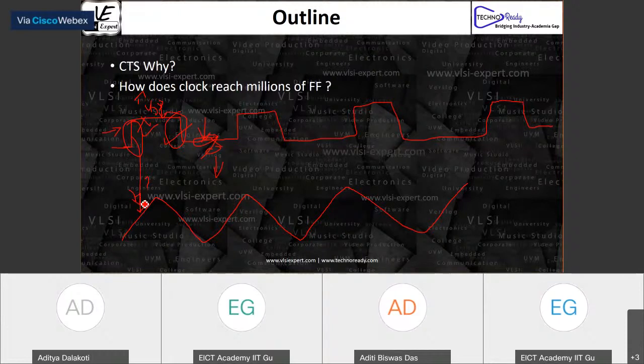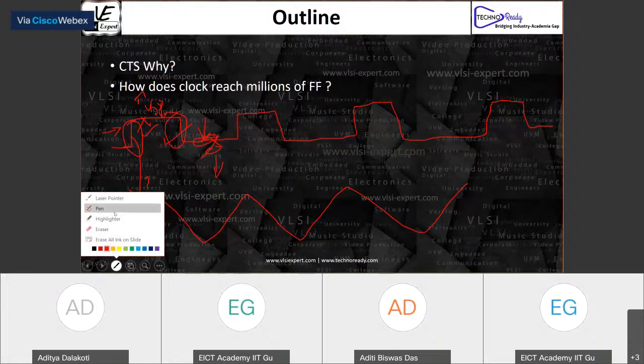Now, if you change this region to this region, if you make it bigger and bigger, the more effect of noise will exist. So to avoid this huge buildup of noise in your clock trees, and to make the clock reach as a clock, so you have the correct frequency and duty cycles delivered to all your flip-flops, is one of the reasons why you create a whole clock tree buffer distribution.